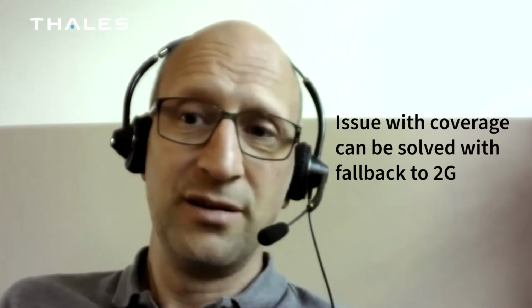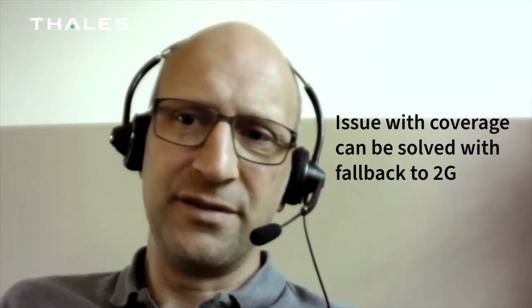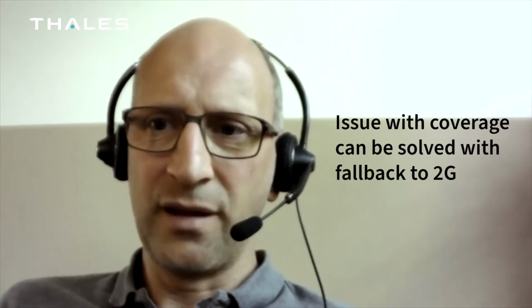But finally, as in our EXS82 module, there would be the possibility, for example, to do a fallback to 2G, where we have the best coverage, I think, worldwide. But to get over this, a state machine in the device should handle this situation, should check the network status, or if the server side could be reached, and if not, do a fallback to 3G, and finally return to the power-saving technologies like NB-IoT or CAT-M.